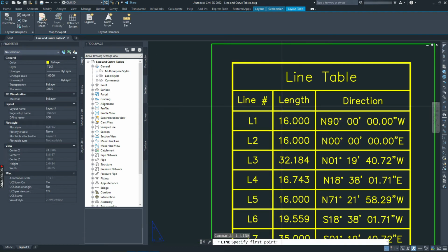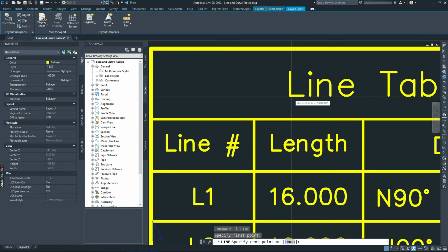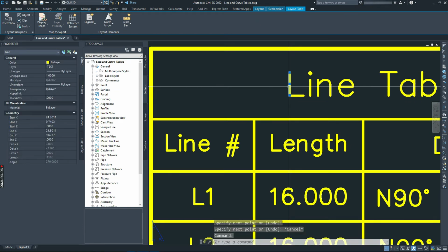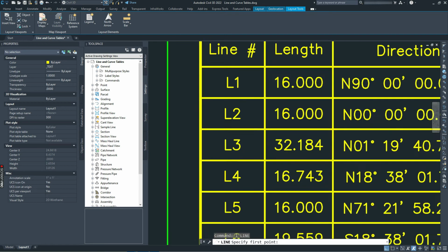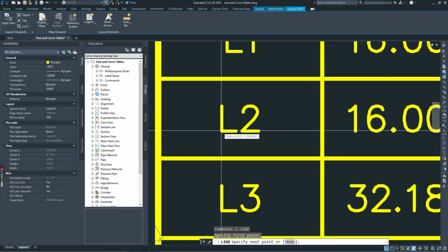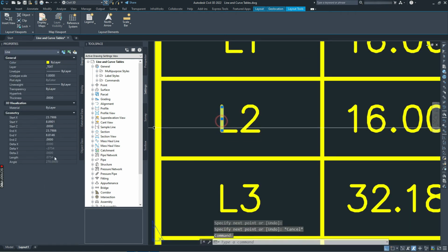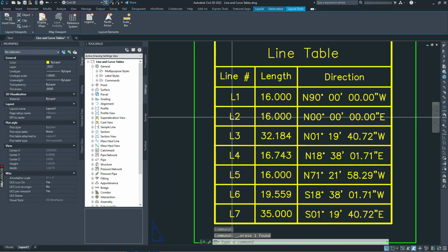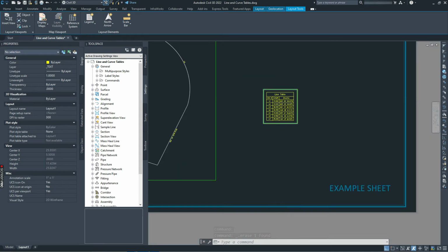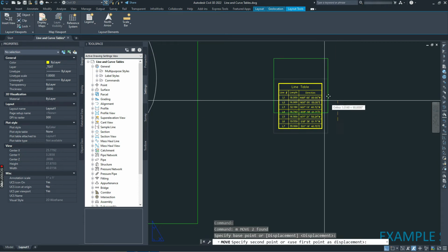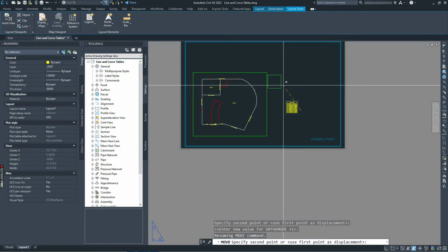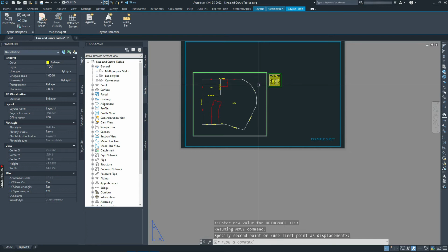And if we check once, our text height up here, remember, was 0.12 for our title, and sure enough, 0.116, that's pretty close. That's right what we're looking for. We can tell that it's 0.12, and down here, 0.08 must be the text height through here. So that's great. So I now have my line table in Paperspace that I can print. And I can set it wherever I want in Paperspace.